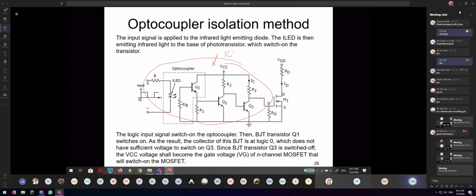That's why nowadays, all the manufacturers will simply buy the IC, then directly configure the IC to drive the MOSFET. So the thing becomes very compact and neat nowadays. It becomes very precise in the design because this circuit is already fully customized. So you don't need to design from the beginning nowadays.